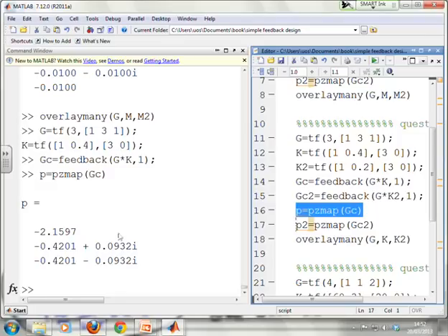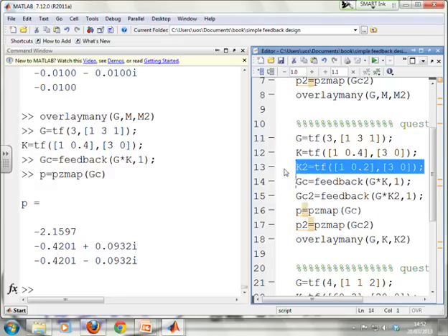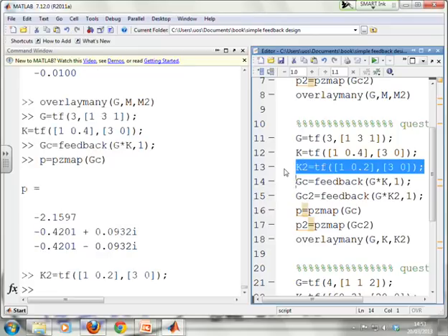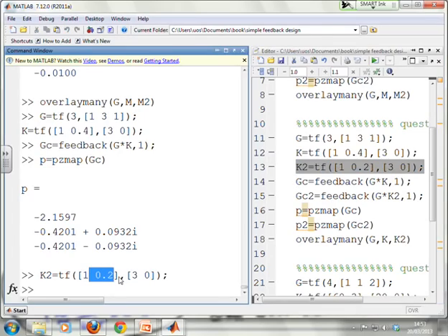Now what I'm going to do is also add the compensator with this typical second order guidance, where you treat the integral as being half of what you get for first order system. So you'll see k2 has got this 0.2 here, whereas the original k we had 0.4. So we've halved the integral, because that's what you said the guidance was for second order systems.